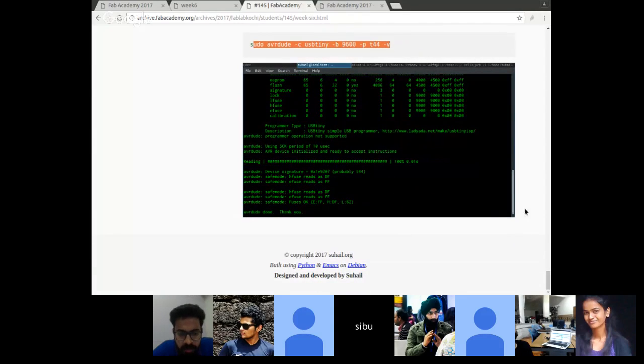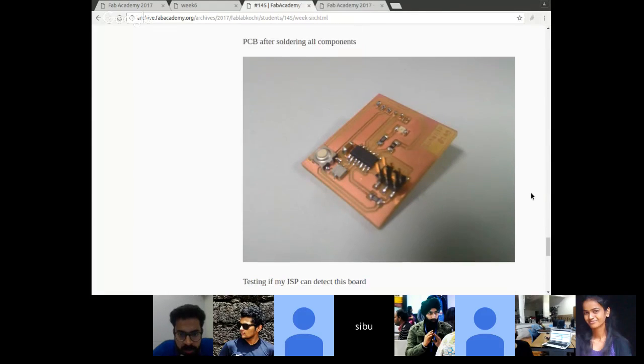Okay, so read more about the pull-up resistor. You're connecting this switch in parallel with the resistor to the microcontroller. Is that the case on the PCB? No, I didn't connect it in parallel. Actually it should be parallel, but I connected it serially from this IC. The switch is in series with the resistor, and this and the next pin are connected to ground. So okay, it was actually wrong.